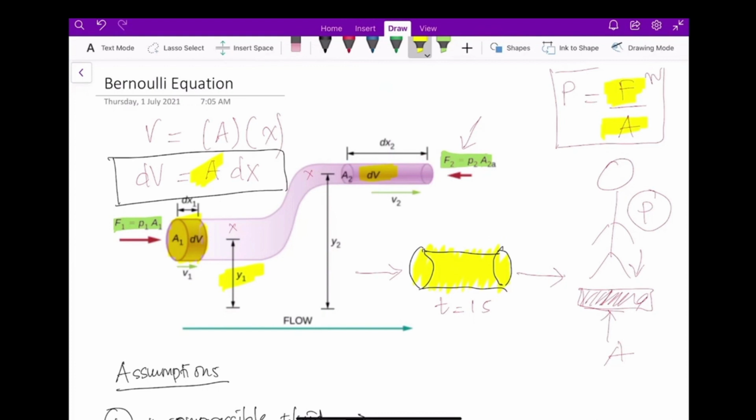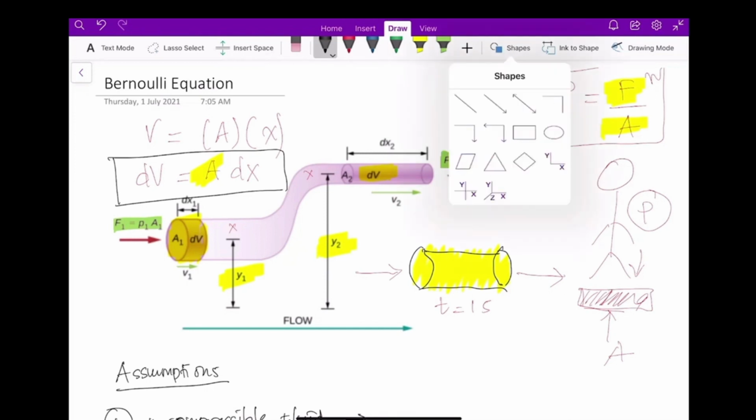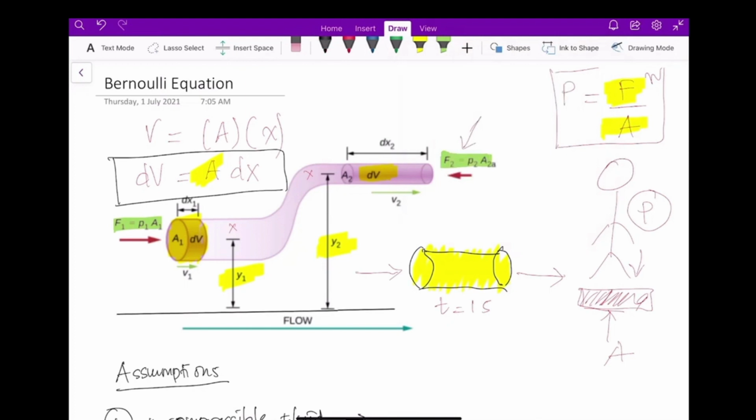Again, it's just a notation; you can put any different notation that you like, not necessarily y1, while h2 is given the notation y2. I forgot to mention earlier, anytime you would like to solve a fluid mechanics problem, you need to ensure that you place a reference or datum level. The datum level for this case will be here. That's why the elevations h1 and h2 are counted from the datum level, the reference point that we are assigning here.